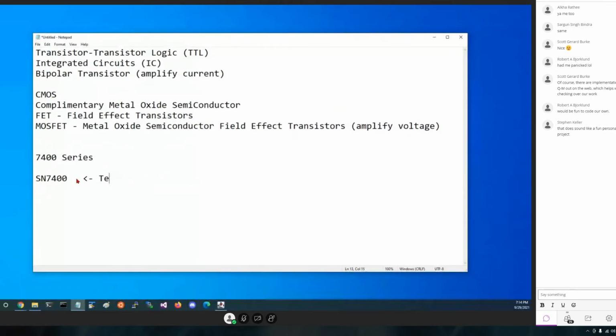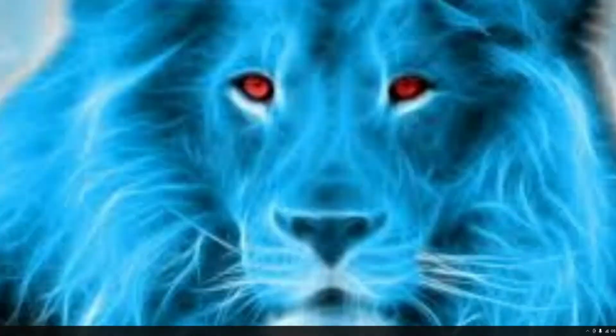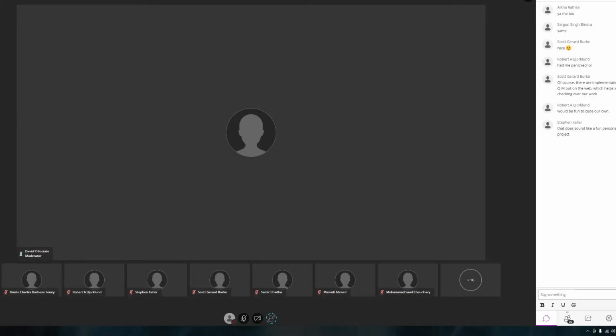Now, additionally, sometimes we will find on the right-hand side of it something like a P or a PD. This is where packaging information goes. This is in something called a plastic DIP. DIP, dual inline pins, meaning it has 2 columns of pins, P, plastic, made out of plastic casing. We'll forget about that for the moment. Also forget about the SN, it's not critical.